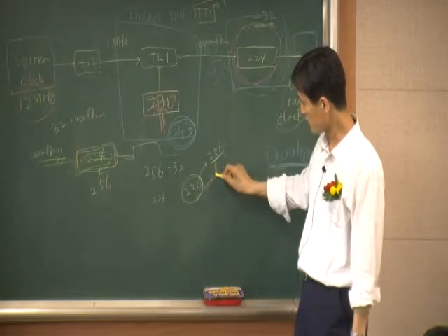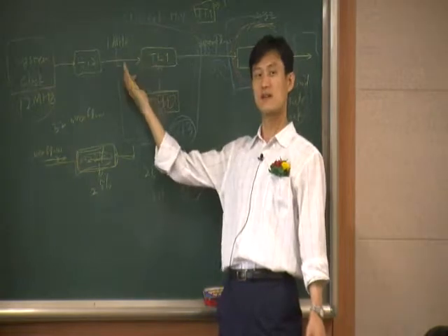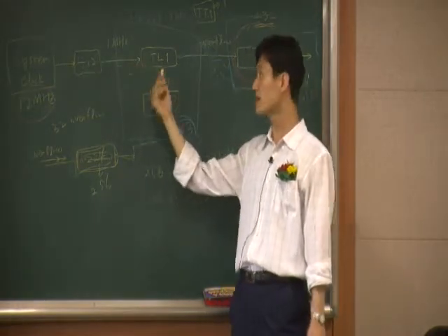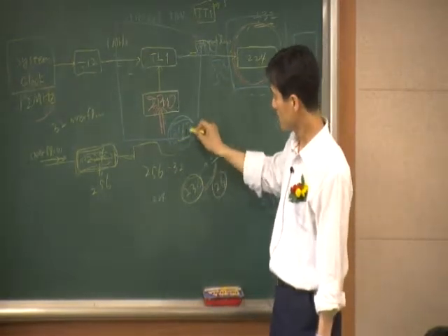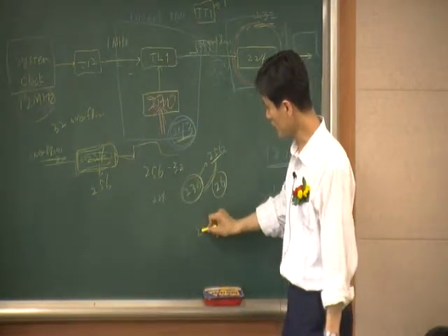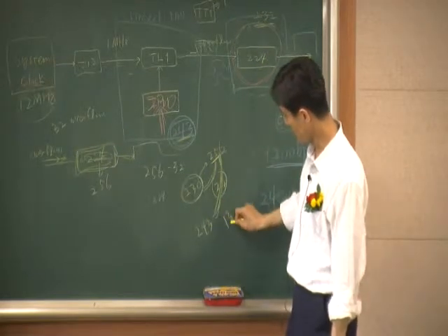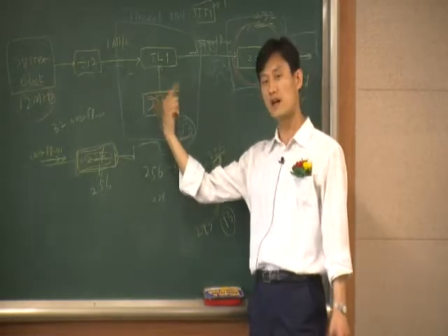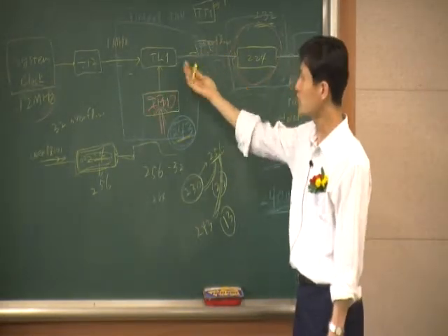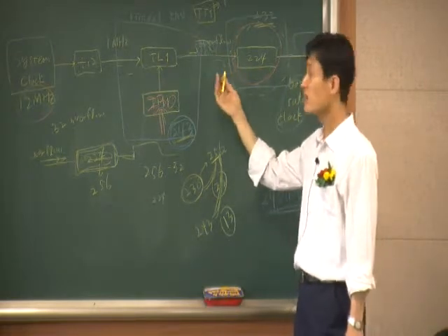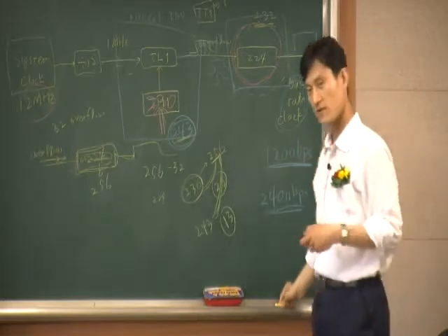And between these, you have 26, so you need to get 26 clocks, then you have a timer overflow. But if you use the initial value of 243, then the difference is only 13. So when you have 13 clocks, you get overflow. Therefore, this overflow is now twice as fast, and everything else is twice as fast.